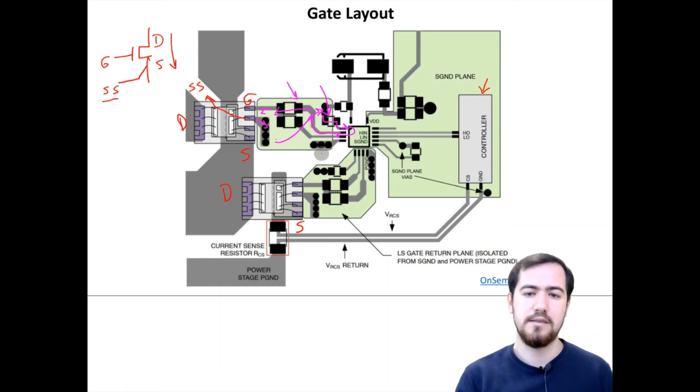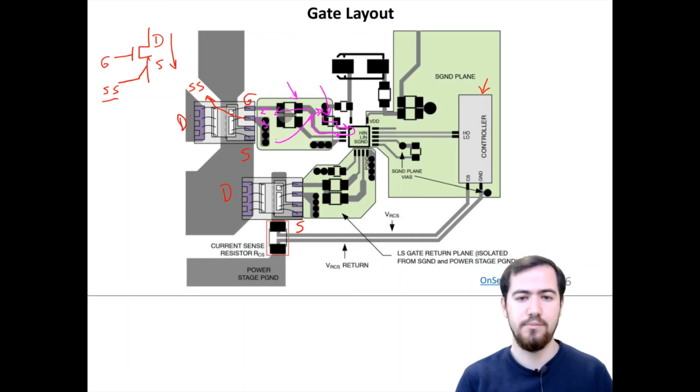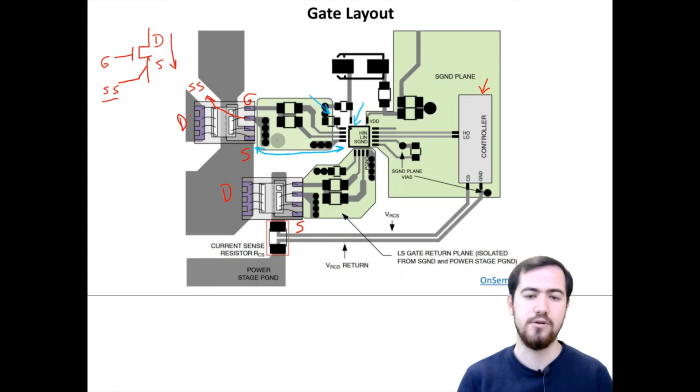And the similar thing happens for the turn off moment as well, but the most important thing is that let me clear once more. Okay, let's clean them as well. I would like to draw with a different color. The gate driver capacitor and the gate driver IC are very close to each other. Moreover, our switching component and the gate driver IC are also close to each other.